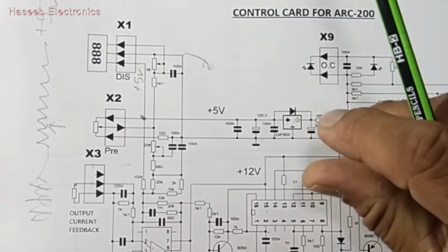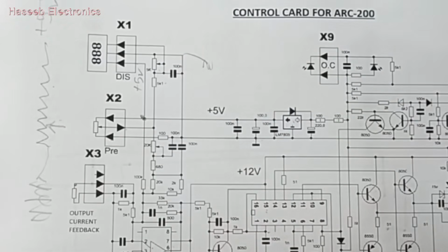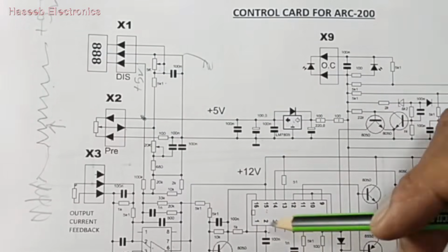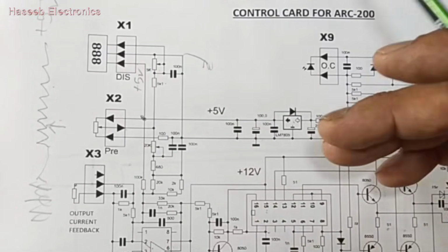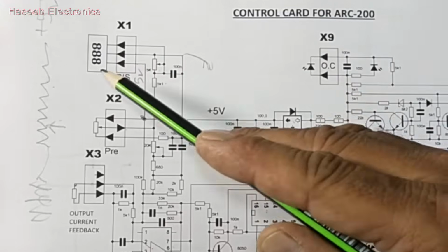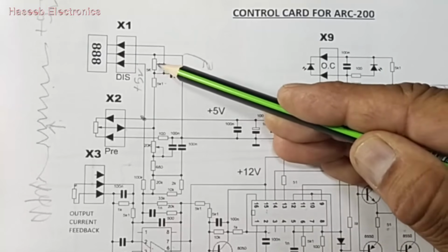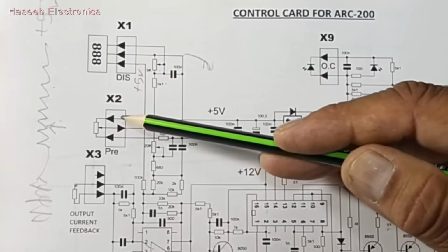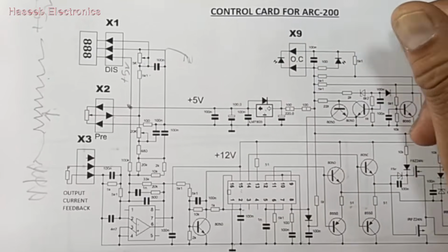In some machines, when we rotate the knob fully to the end, for example a machine for 200 ampere will display only 150 or 160 ampere. So we have to increase or decrease this resistance to get a full rated measurement at full rotation of the potentiometer.